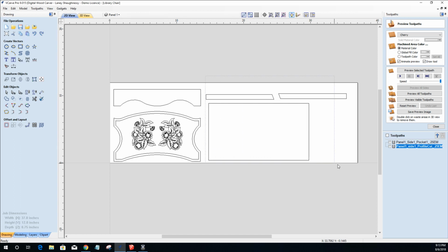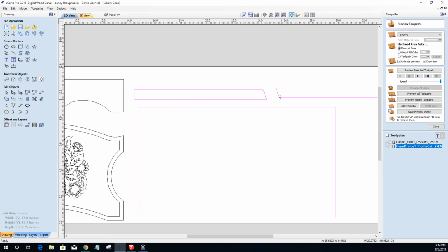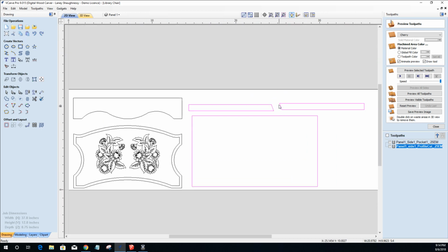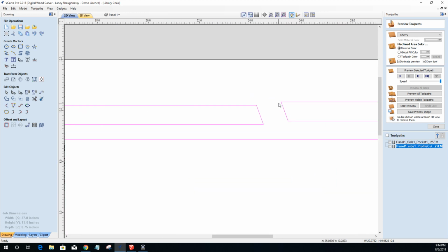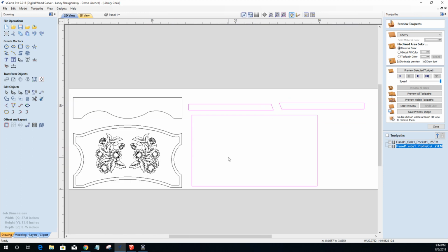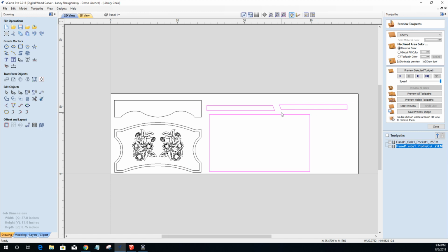And these 3 parts here don't necessarily need to be cut on the CNC. I mean, they can. There's nothing wrong with it, but they're square cuts, other than the 20-degree angle cut on the end, of the 2 shelf boards. These are not the shelf boards. I'm sorry. These are the splines for the lower side of the legs. Those are the splines, but it's just a 20-degree cut, or 70, however you want to look at it. But those can be cut on the table saw. I mean, they're 3/4 inch wide.